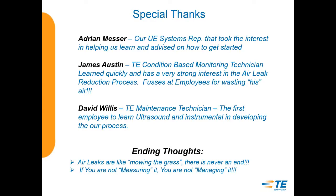All right. And then someone was wondering if, knowing what you've learned now, would you order smaller CFM / HP compressors next time around? That's actually one of the benefits of where we're at right now. In the main compressor room that I primarily talked about, we've got a 200 horse primary, a 200 horse trimming, and a 250 horse backup.